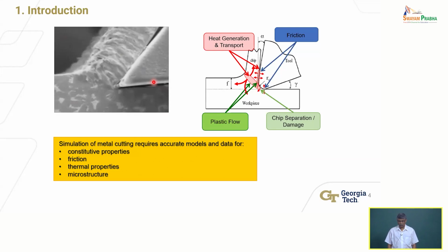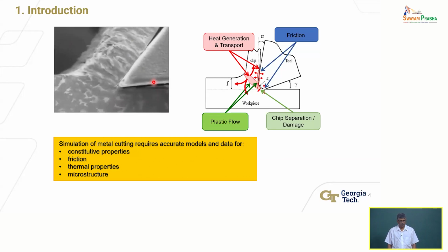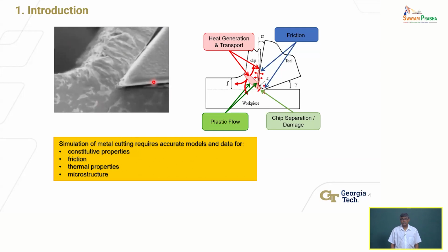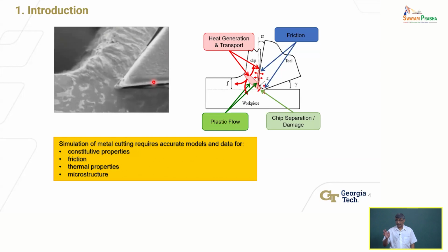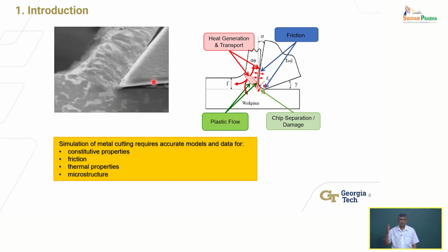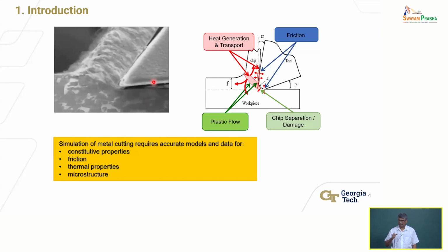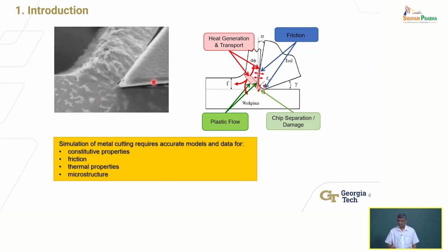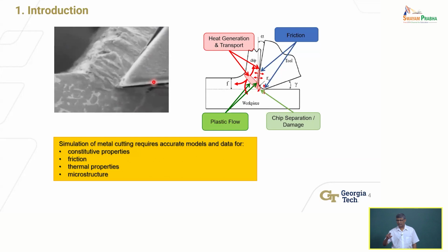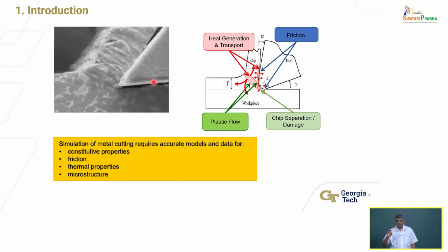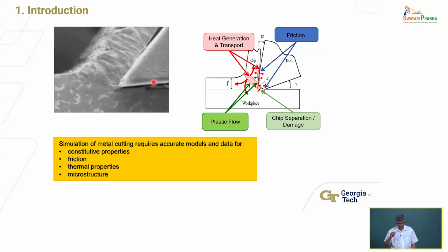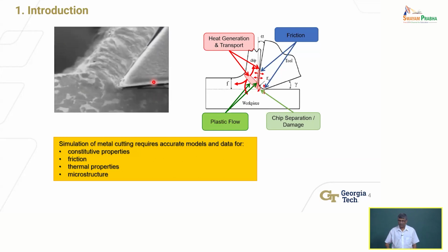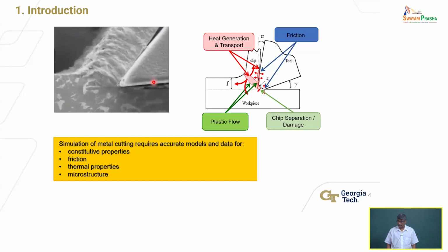Thermal conductivity is one, right? Thermal conductivity is one. What about other? I'm sorry? Thermal expansion, potentially, but for certain aspects of the problem, yes, but not for the plastic deformation. We are talking of severe plastic deformation, right? So thermal expansion can occur, most certainly, and what it'll affect would be the depth of cut and so forth. But I'm really talking about something that allows me to describe accurately how this material is behaving, right? So thermal conductivity certainly is one, okay?